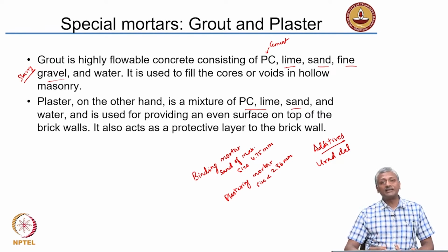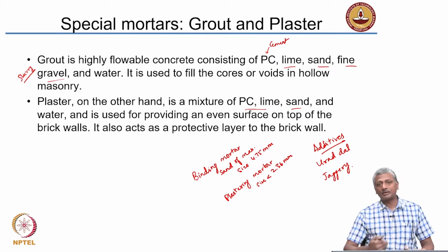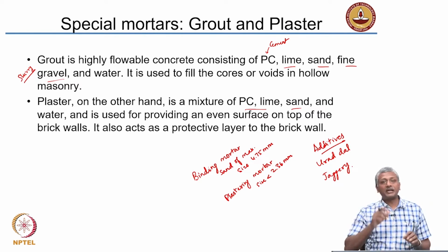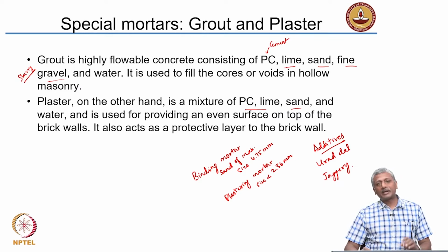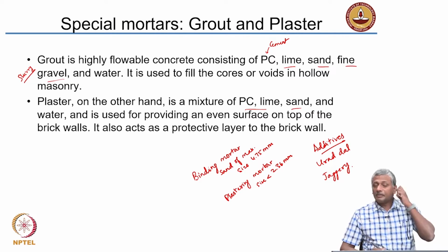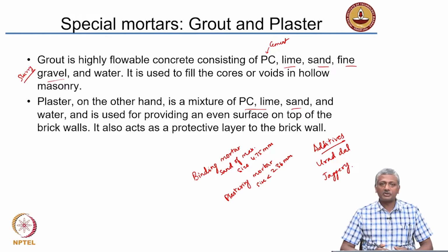In South, you will often find that jaggery is being mixed in the mixture of lime and water. They mix jaggery also with lime, mortar and water, and jaggery imparts a nice water retentive quality to the structure. So, depending upon the application and depending upon the geographical location, there are practices that have thrived, that have actually stuck on from age old times, which are still being followed, especially with the construction practices with lime. So, you will see that depending upon the geography, depending upon the location, you may actually get very different practices as far as lime mortar preparation is concerned.